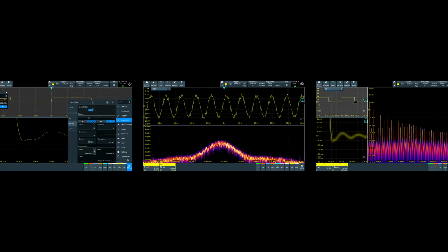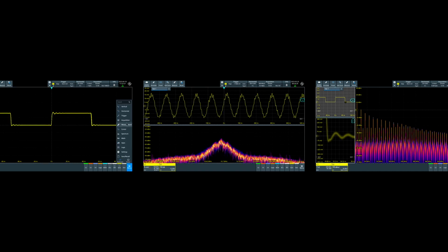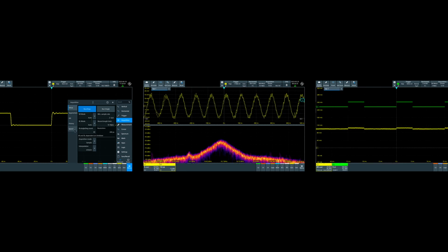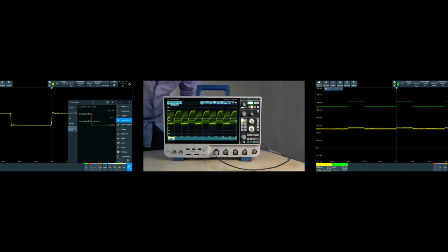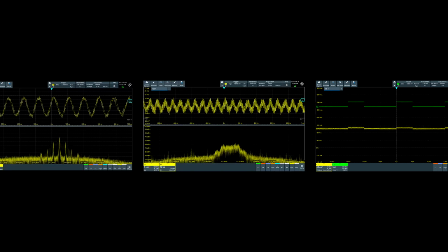In terms of functionality that is missing, I'd like to see a remote command available for exporting the spectrum view. With the current firmware, it needs to be saved as a file and then transferred. I think that the math channels should be extended to allow chaining more terms. The instrument seems more than powerful enough to handle it if they would just enable that in the firmware. I also hope that they can enable custom button configuration too. There is a user configurable button, but it doesn't do anything currently. I want to set it to open the acquisition menu, because that seems to be something that deserves a physical button on the scope.